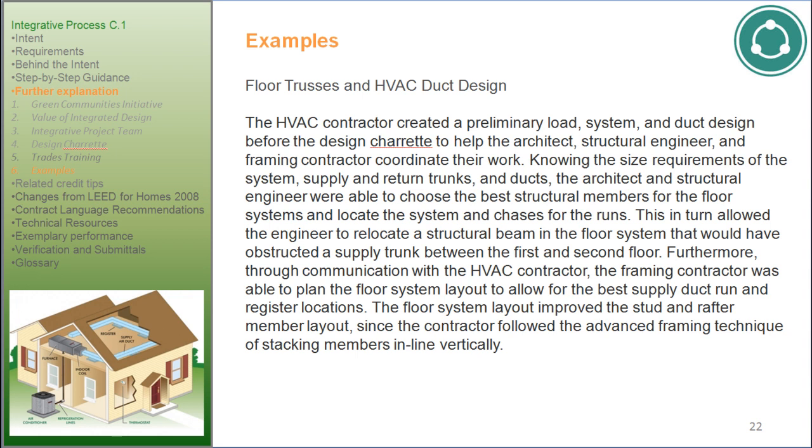Another example from further explanation: floor trusses and HVAC duct design. The HVAC contractor created a preliminary load calculation and duct design before the design charrette to help the architect, structural engineer, and framing contractor coordinate their work. Knowing the size requirements of the system, supply and return trunks, and ducts, the architect and structural engineer were able to choose the best structural members for the floor systems and locate the system and chases for the runs. This in turn allowed the engineer to relocate a structural beam in the floor system that would have obstructed a supply trunk between the first and second floor.